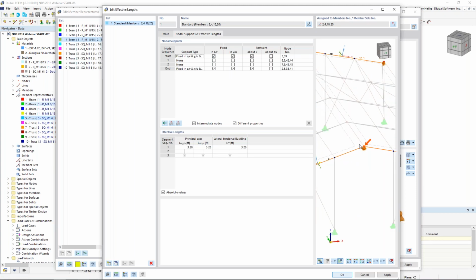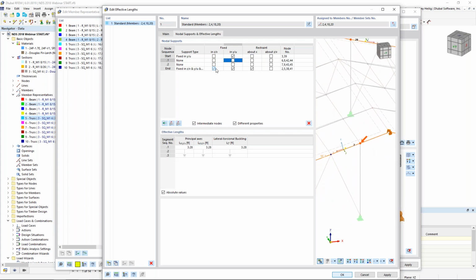Well, notice we only have a truss member framing in the weak axis direction. So I probably want to add this intermediate restraint here to only restrain my tapered element in the weak axis or local Y direction. For node number 2, we have a column framing up. So I'm going to assume that this element is restrained in the vertical Z direction, as well as in the weak axis direction from my truss, as well as rotation against torsion at this location.